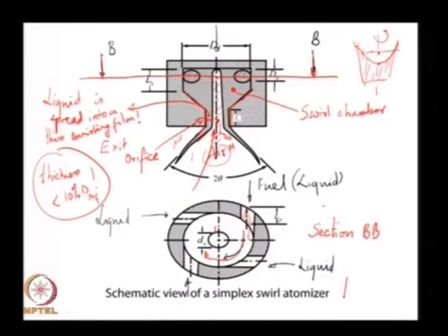very thin film, the film thickness is one of two determinants of the final drop size. The film thickness is very small. Okay, we will see the benefits of this in a moment, but the interfacial area of interaction between the air and the liquid is now twice as much as I had the chance to create in the diesel injector.